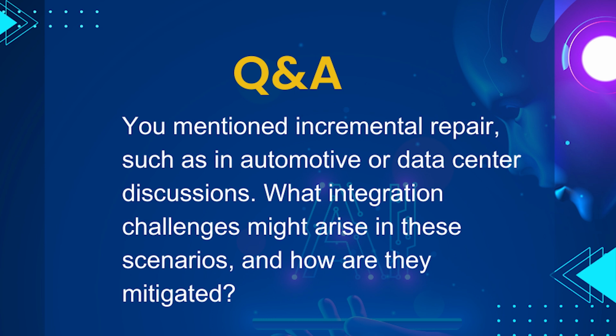It may need multiple times the capacity. Second, low power operation of non-volatile memory. For example, program power is sufficient and important to support in-field repair. In-field programmability is a major advantage of NeoFuse OTP. And we designed these solutions to fulfill the requirements of high-reliability automotive applications, data center usage, or AI applications with large SRAM.